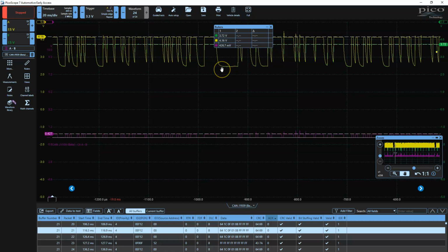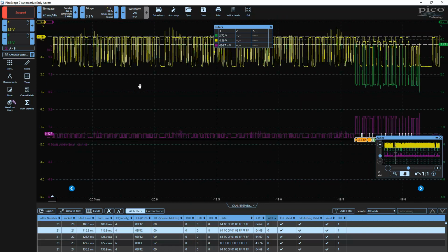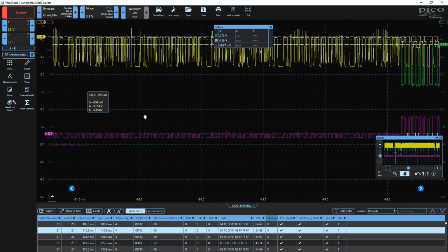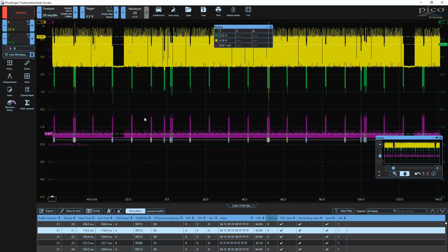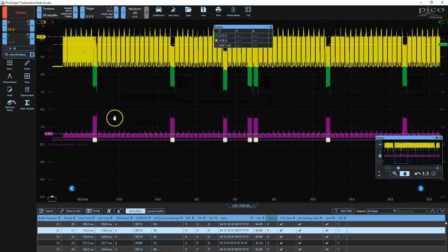And so we end up with a difference in voltage between CAN high and CAN low such that we can't determine what's going on. As I indicated, I can't even tell which controller this is, because the threshold is below the point where the scope is able to interpret the message. We can see that for sure the messages are definitely being affected by this. It is definitely impacting the bus.